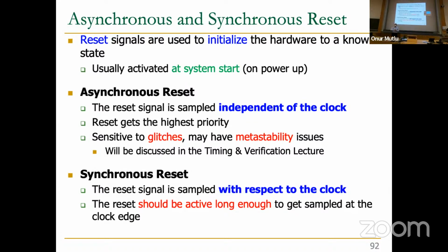When you're receiving signals from the outside, for example, that's completely asynchronous. The outside signals have no knowledge of the clock. So if you assume that the outside signals need to be sampled at the time the clock changes, then you may be missing some of those signals. You really need to add some asynchrony to the circuit. And that's important to think about. So there's some domain that needs to transition from asynchronous to synchronous if your computer is completely synchronous.